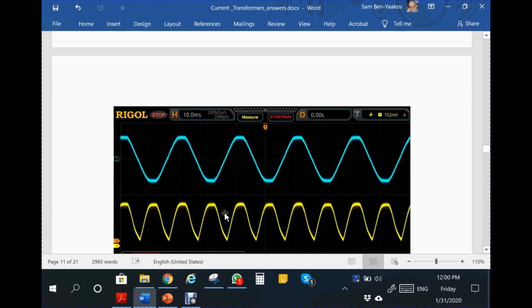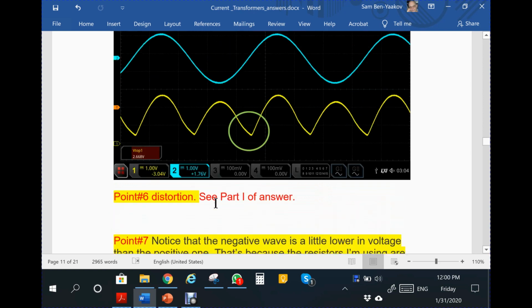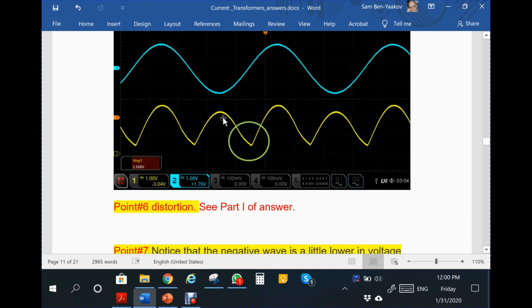It just doesn't make sense. Either they affect the accuracy, and then you expect to see here also the same difference, because you're using the same resistors and the signal goes through the same path. Now I would suspect that the reason for this asymmetry has to do with the fact that rather than having the voltage coming out of the current transformer, it's now coming out of the function generator. This is the output of the function generator, and not from the current transformer.